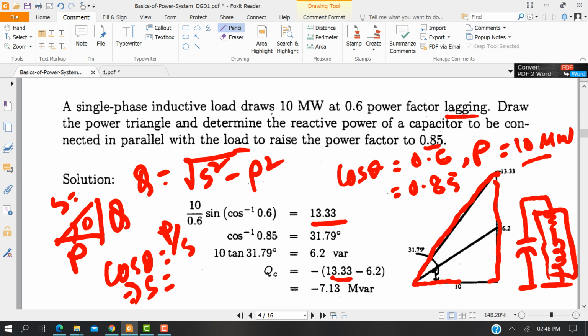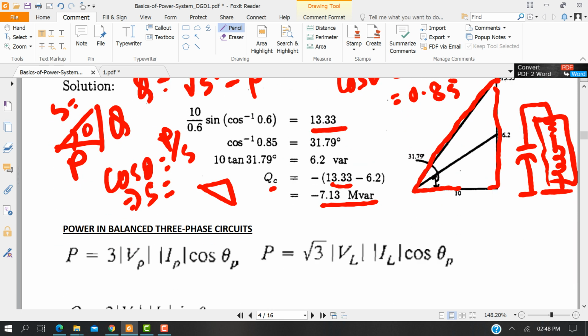So what is the reactive power improved by the capacitor here? So just subtract this and there is an improvement. And why is there a minus sign? Because as I said earlier, Q is negative for the capacitive reactive value, because it just goes down. Though I drew this figure here, it could be like this. This is the negative sign, just ignore this, no problem with that. It should be S and Q. All that remains. This is a theta.